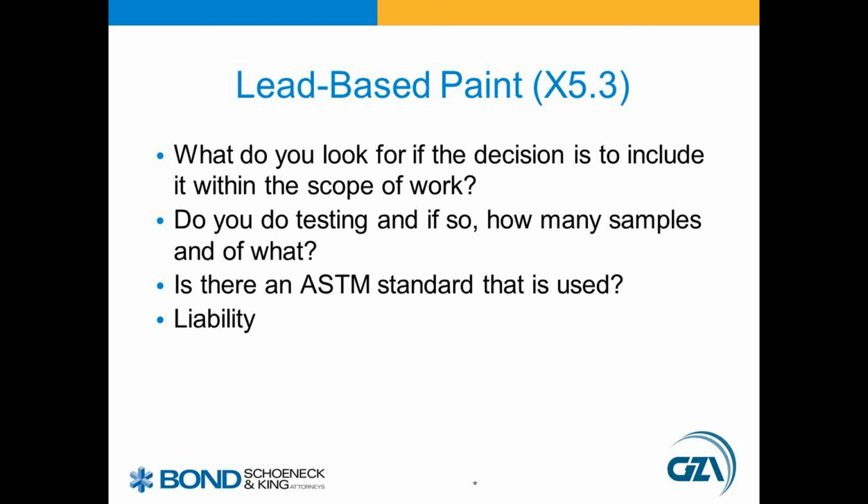Another possible rule that comes into play, going on the EPA website, is the EPA's lead renovation, repair, and painting rule. The website notes that it requires that firms performing renovation, repair, and painting projects that disturb lead-based paint in homes, child care facilities, and preschools built before 1978 have their firm certified by EPA or an EPA-authorized state, use certified renovators who are trained by EPA-approved training providers, and follow lead-safe work practices.